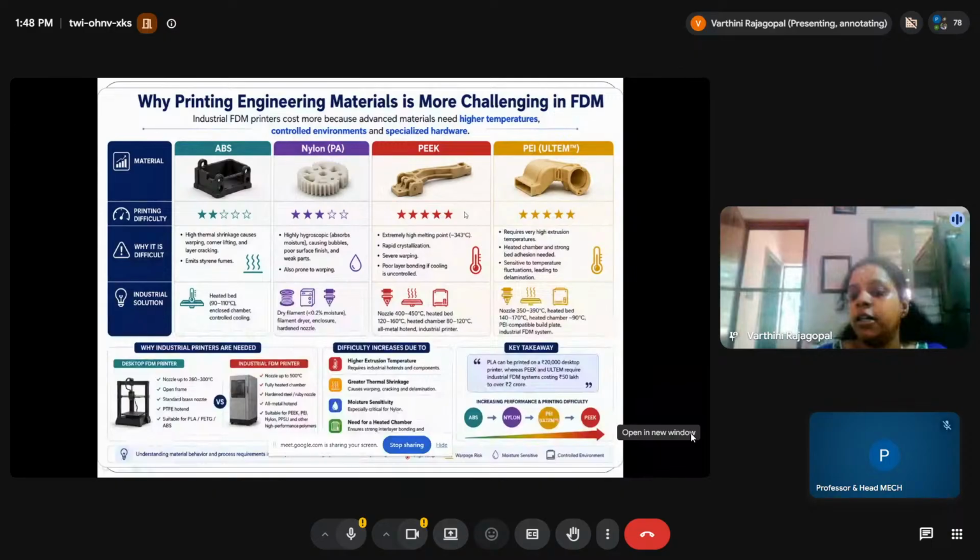Yeah, so I want to give a glimpse about PEI, because if anyone is going to choose the aerospace sector, PEI is your ideal thermoplastic. They are flight approved, flame resistant, chemical resistant, lightweight, and they can be FDM printed.